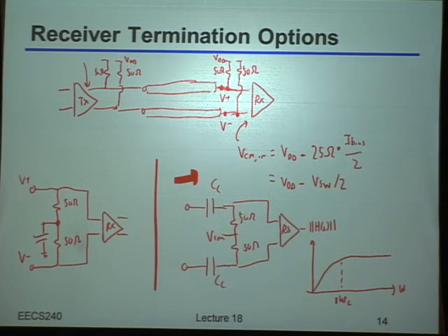Okay, so in some systems, there is no coding. There's nothing that stops you from sending as many ones as you possibly want. By the way, a typical example of that is something like a memory interface. Because in those memories, they care about every single last square micron of die area. So they want to spend absolutely zero on doing anything in addition. So a lot of times those are DC coupled and have absolutely no coding on them whatsoever. So if you just happen to be unlucky, you can get really, really long strings of ones. That's not to say that practically you'll really ever get an infinite string of ones, but you could get something that's long enough compared to that corner frequency that you really start losing your data.